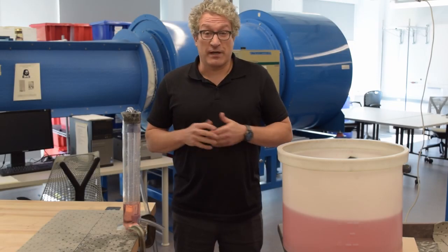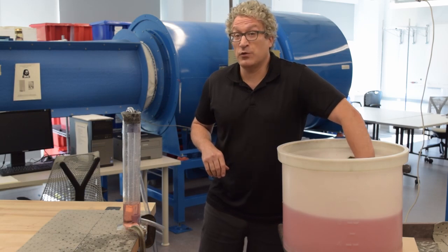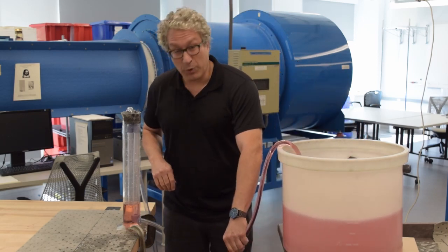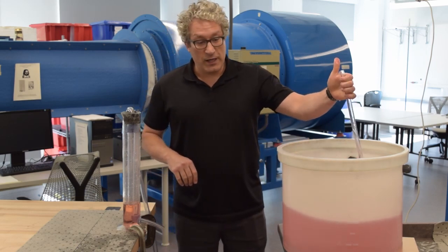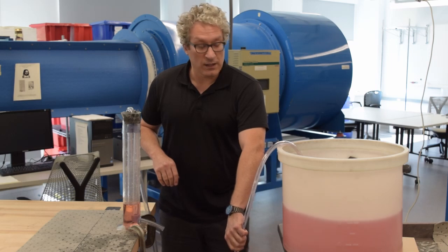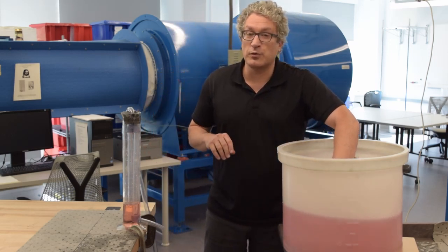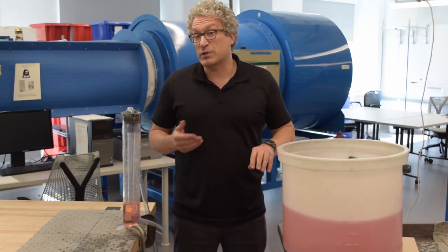Now, there are other types of siphons. We talked about a siphon that just had a tube that we either filled with water or didn't. When we filled it with water, it was effective at pulling water out of a reservoir. If we let it empty and it had only air, it wasn't effective in moving anything at all. If we could design a system that oscillates back and forth between these different states, then we can take something that has a steady input and create bursts in output.